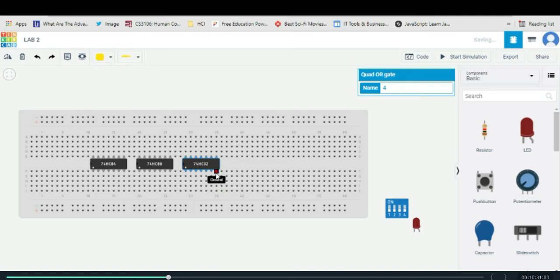And the same pin number for the ground. So as you can see, if you point the mouse pointer at each leg, that indicates whether it's a power, an input, an output, or a ground. The 7404 has only one input per gate but six gates, I guess, six inverters inside. So the next here is the output, something like that.